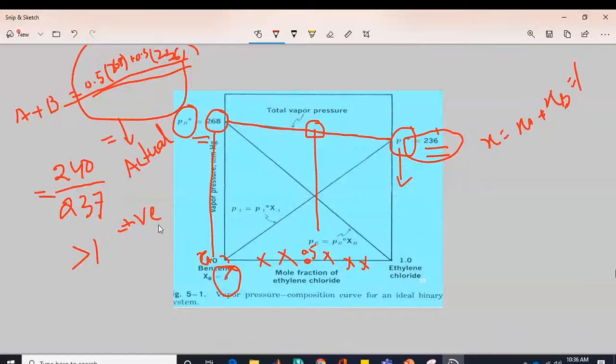Let's talk about this principle. A liquid boils when the vapor pressure is equal to atmospheric pressure. Yes, we know that. If the external pressure is reduced by applying the vacuum, the boiling point of the liquid is lowered. Yes, we already discussed that. Therefore, the liquid boils at low temperature. This principle is illustrated by using an example of water. Water boils at 100 degrees, we know that, at an atmospheric pressure of 1 atm, or 101 kPa, or 760 mmHg.